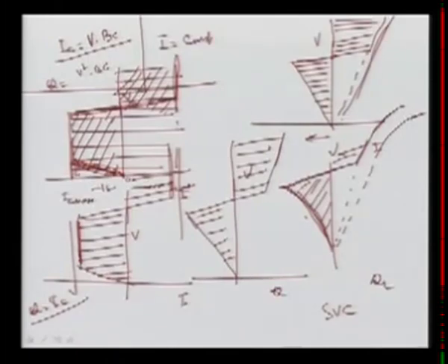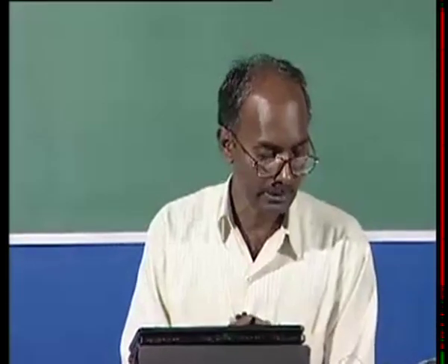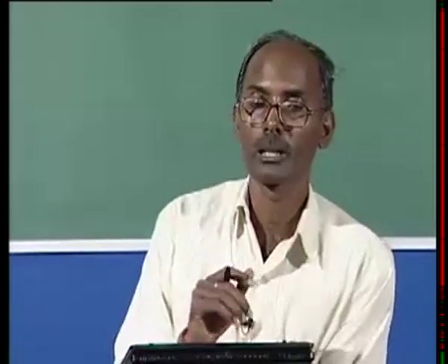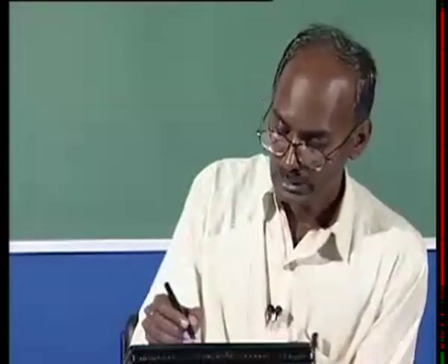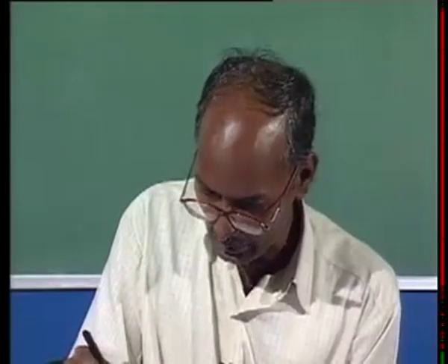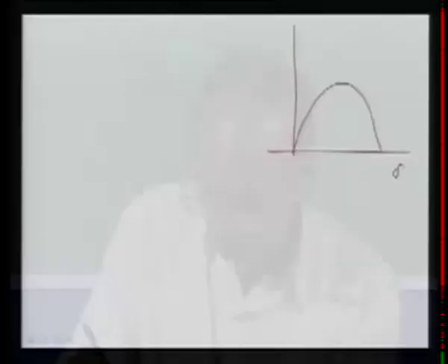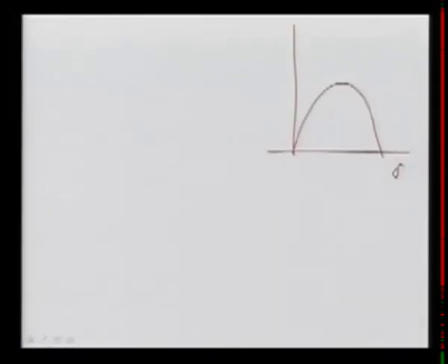Now let us see another major difference. When I was talking about the P-delta curve, if you remember, this is your delta, and I said this is without compensator. If you compensate, ideally we go to double this. When there is no limit in the midpoint compensator, we will achieve this P-delta curve. This is without compensator, this is with compensator.